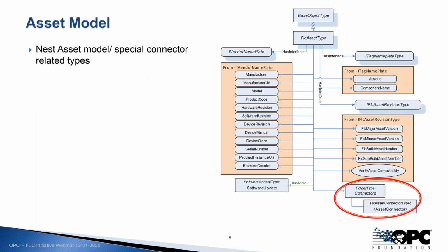So we have the capability of asset models to actually be nested. So I don't have to have one big model that describes the whole asset. I can describe an asset and describe the fact that the asset has children or submodels as part of it. So I have a PLC with additional I/O cards. So I can model the I/O cards. Maybe I have a controller that has a capability of communicating through multiple additional I/O cards, or maybe it has a description of the field wiring that's connected to it through I/O racks. So all of it can be described in this model.